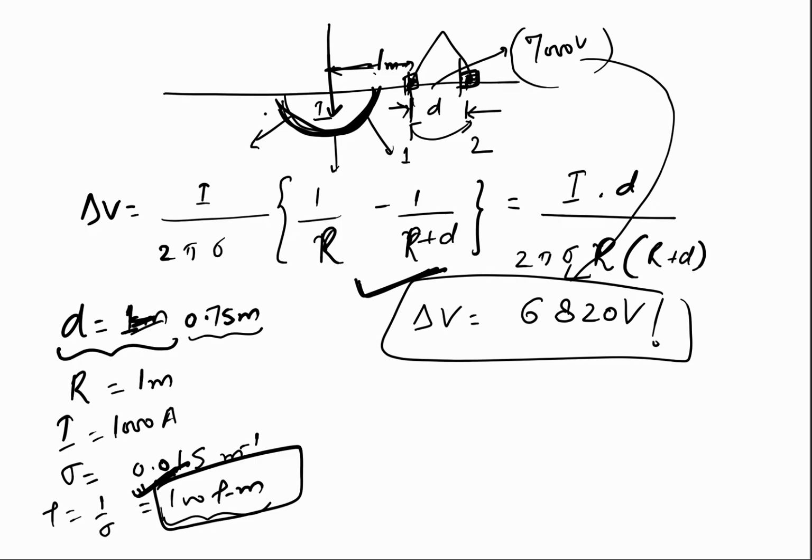Now, in this way, we have shown that the method of image is applicable for current problems, especially for a homogeneous media case, and we have shown how to calculate the ground resistance of an electrode. Now, for you, I will leave a numerical question for practice at home.